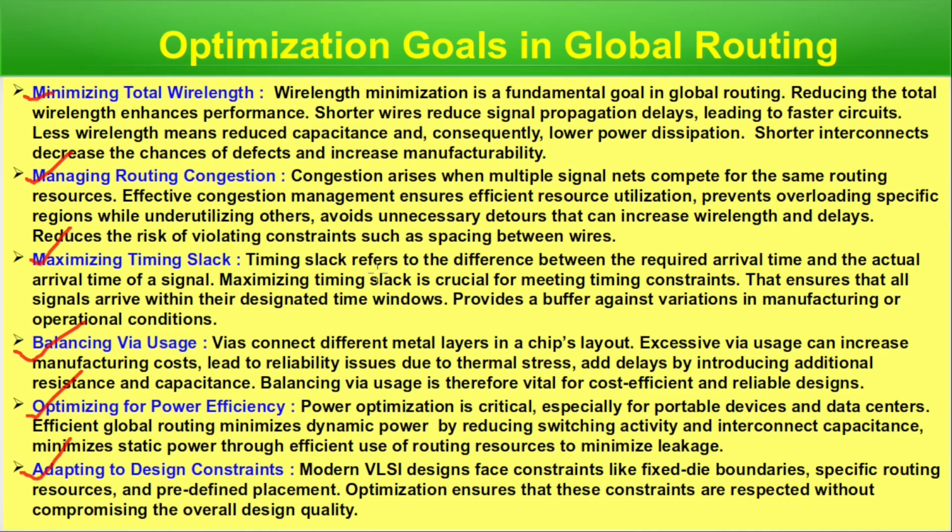Vias connect different metal layers in a chip's layout. Excessive via usage can increase manufacturing costs, lead to reliability issues due to thermal stress, and cause delays by introducing additional resistance and capacitance.